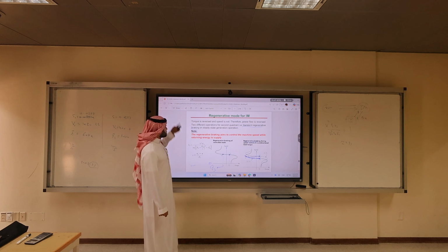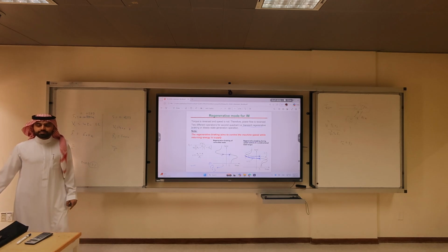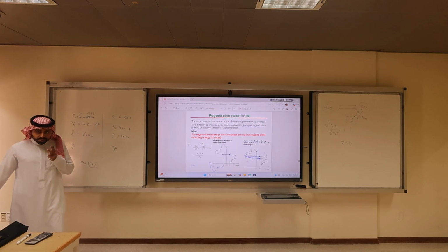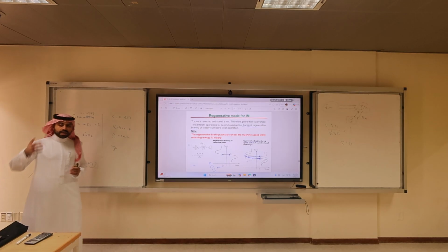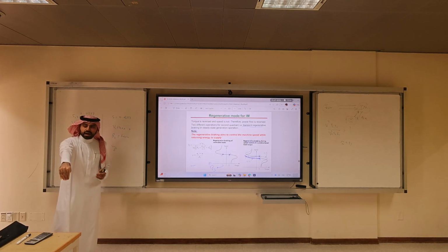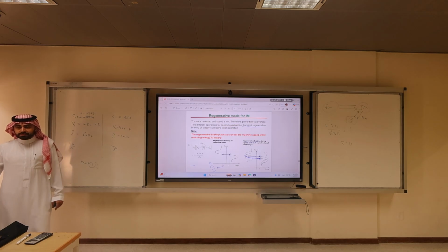Okay? Doctor, in the elevator example, regenerative braking is when the elevator stops? When you check the speed and change the voltage and you want your elevator to slow down, for example, before it reaches the destination, it has to slow down. Think about the towers elevators. They start fast and then they slow down. The moment they slow down, it's regenerative braking. But the torque is still positive anyway. I know, but this is transient.